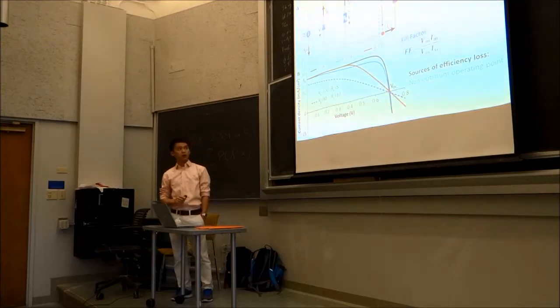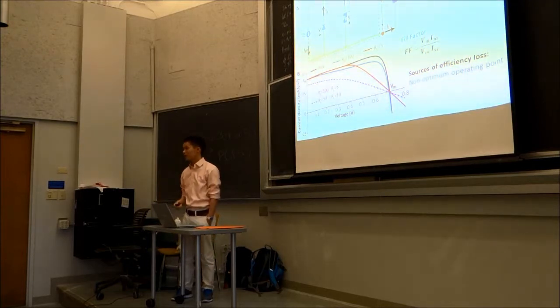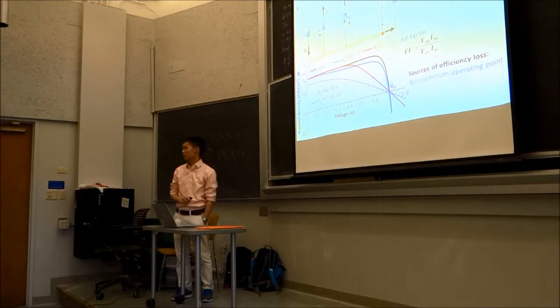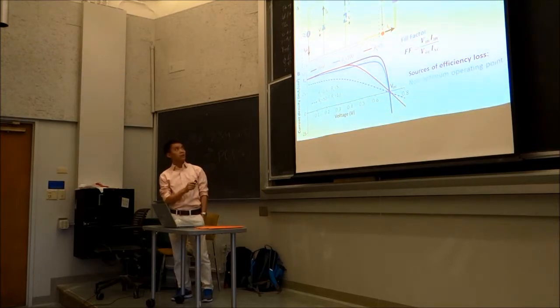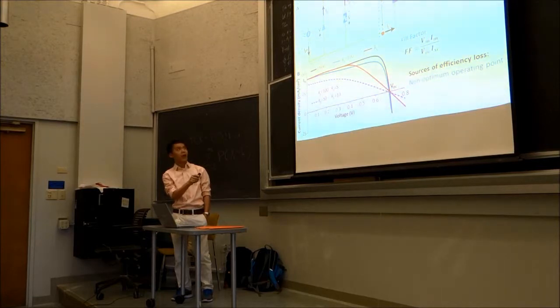And this is another one talking about the IV curve. If you talk about photovoltaics, then people expect you to know something about the IV curve. The photovoltaic cell we talk about can be modeled in an electric circuit as this current source as well as a diode here. And if you model this, you will end up with some IV curve like this. This is the current, this is the voltage. Essentially, when you have different voltage here, you have different currents.